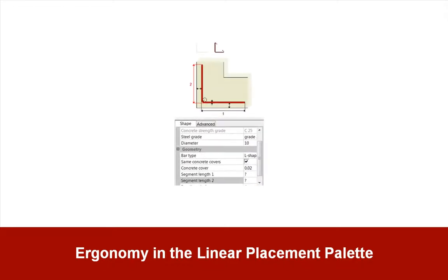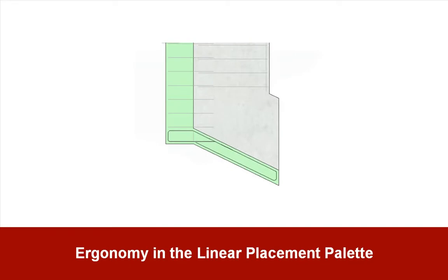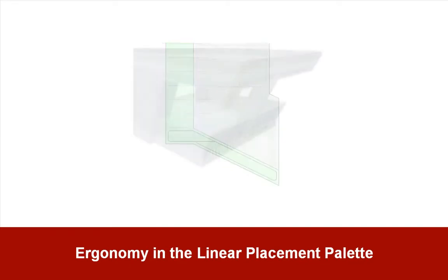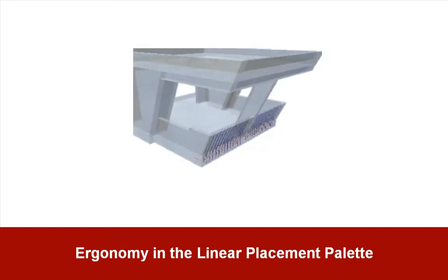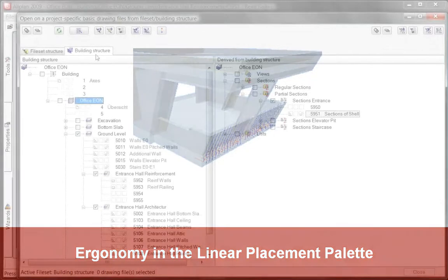One of the areas which was focused on was the ongoing development of palettes, which we had introduced in version 2008. In Allplan 2009, you can create a bending shape and now use the placement palette to place it linearly in either edge-based or segment-based mode.